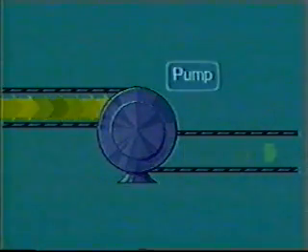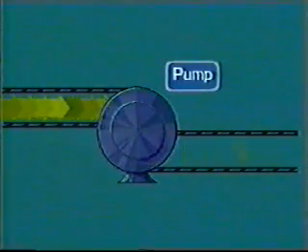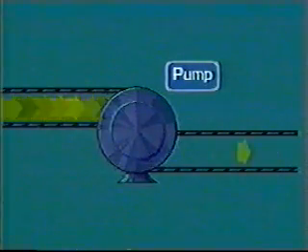Pulsation can also be a factor in metering accuracy. Pulsation can be caused by metering stations too close to pumps, or through inadequate control of the upstream flow. Dampeners can be used to reduce the problem of pulsation.